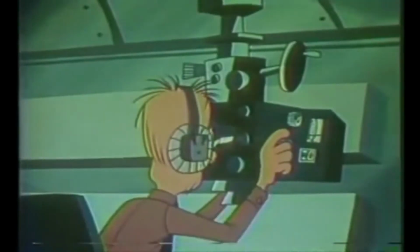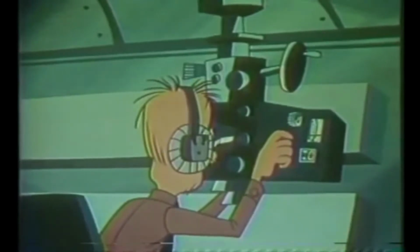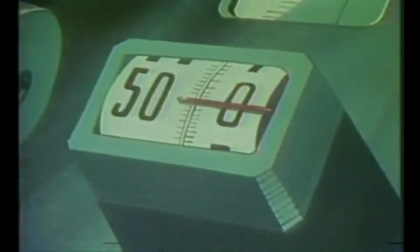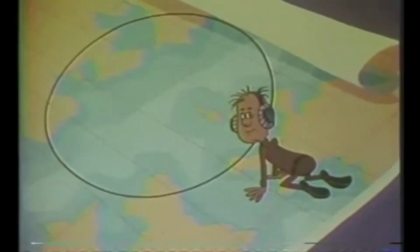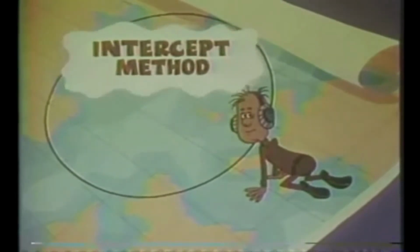Usually, however, you will be observing celestial bodies with altitudes less than 85 degrees. Bodies whose geographic positions will be hundreds or even thousands of miles away from your own position. Theoretically, you could use the first method to plot your line of position if you had a large enough chart. But obviously, you need an alternate. There is one, and it is called the intercept method.